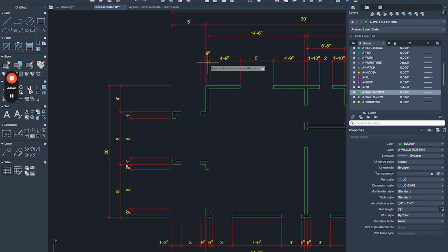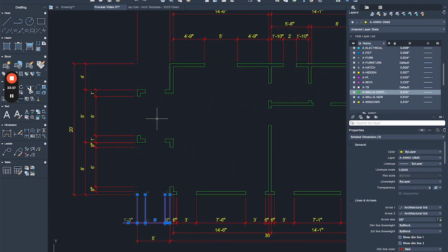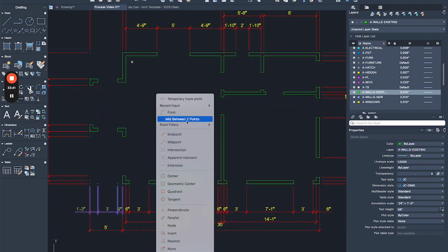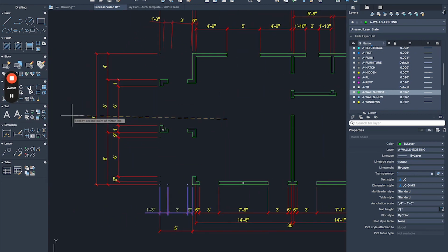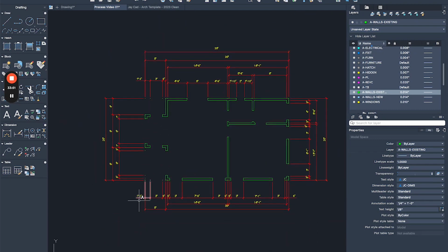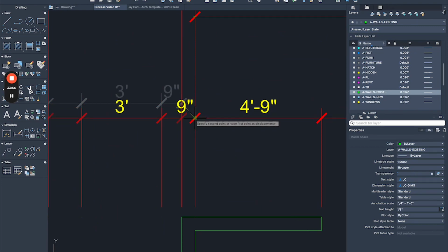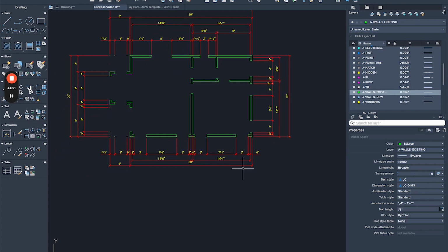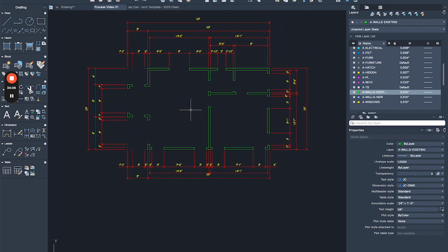Right, and then we have one more. Okay, since these dimensions are the same, I'm literally just going to mirror them. And I'm going to mirror them based on, I don't have a middle point, so I'll do a middle point between here and slide it down here, and then boom, like this. And then do not erase, yep, and then I'll stretch this group of dimensions so they're aligned with here, and this is good, so that way I'm consistent all around. I believe I'm good to go, and then we hit another save.